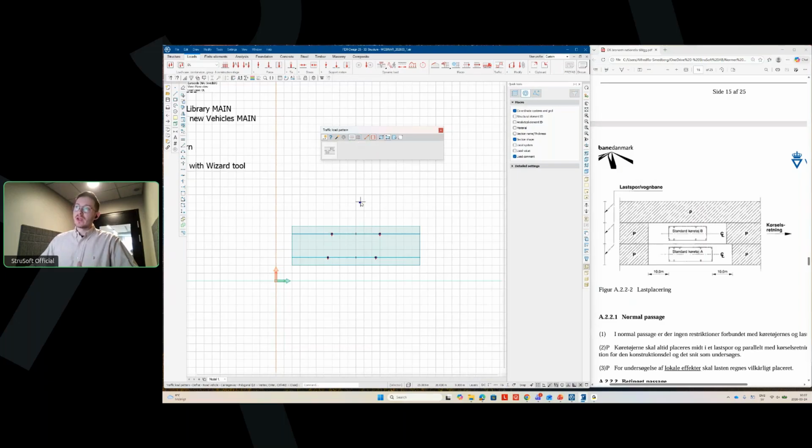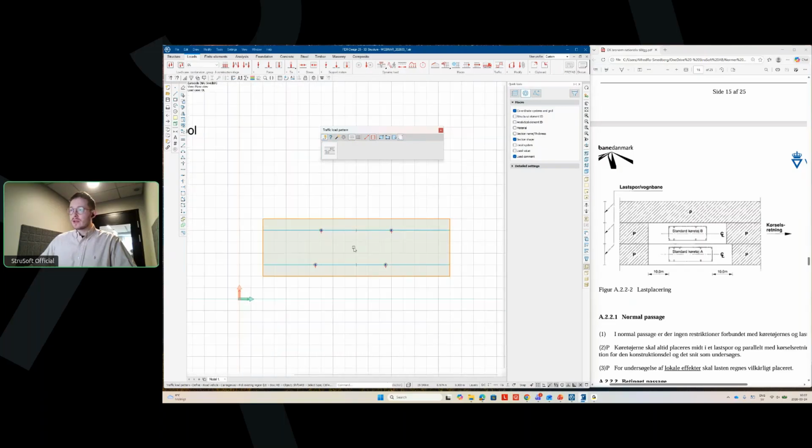And then also depending on if we want to generate loads along a simple line model, or as in this case, we want to place our loads on a surface or a carriageway. And you have several different types that you can draw this carriageway. I will simply use this pick existing region. We have the define tool ready, and then I right click on this surface.